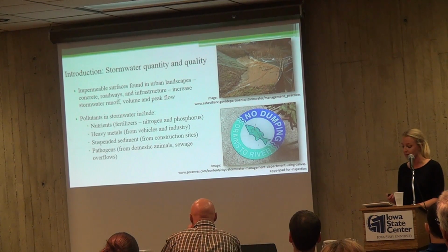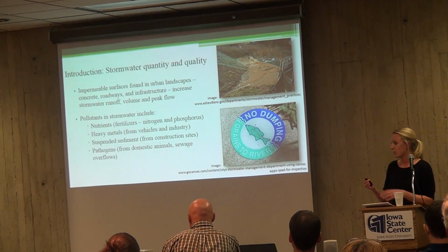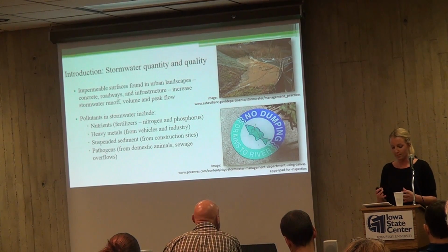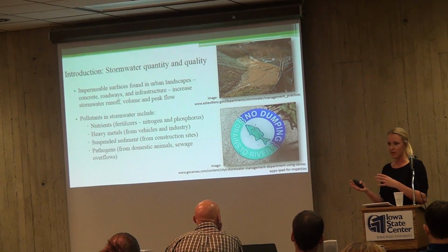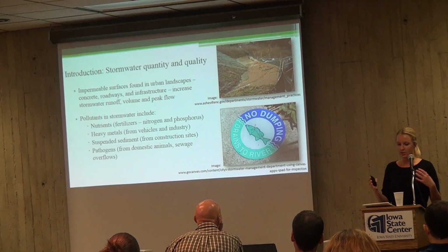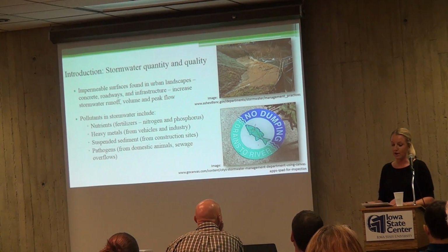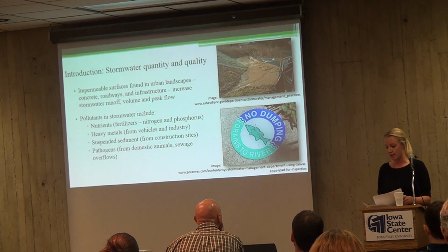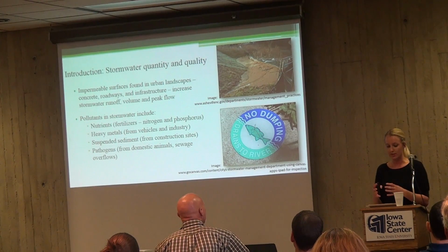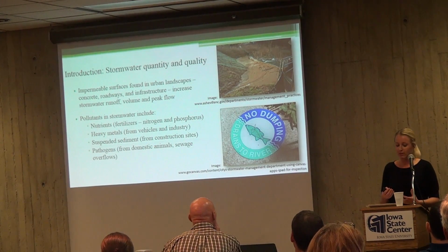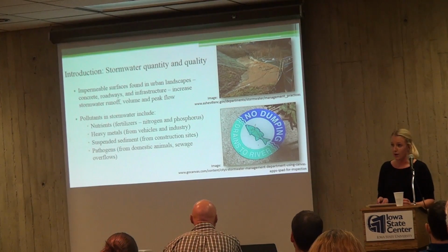Fortunately, stormwater management has considerably evolved over the last few decades. Traditionally, stormwater management had an end-of-pipe system where we wanted to convey water to off-site facilities as quickly as possible, to these centralized municipal facilities. But these combined sewer channels and stormwater in the same conveyance systems, just leading to one big facility. This approach neglected the task of improving water quality and thus has created downstream pollutant problems.